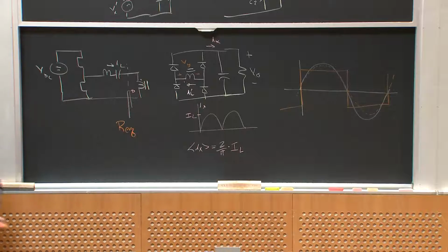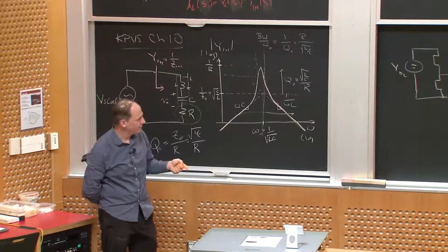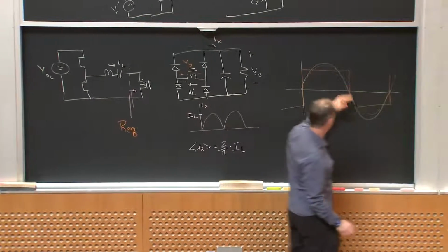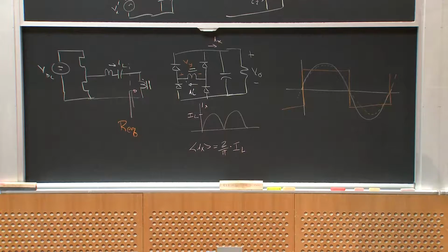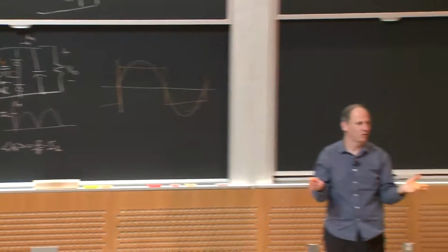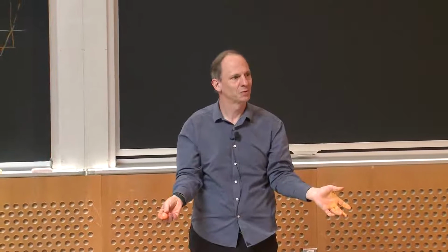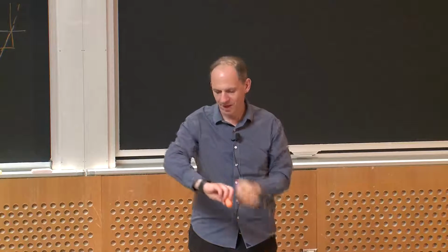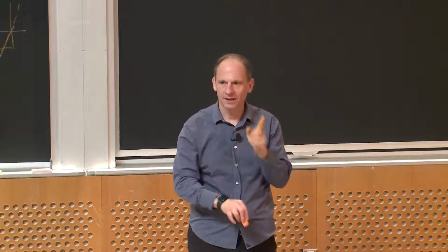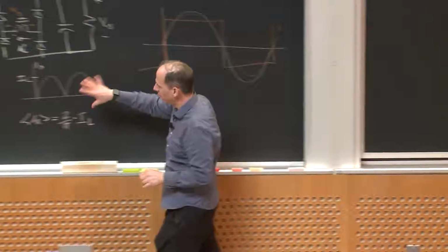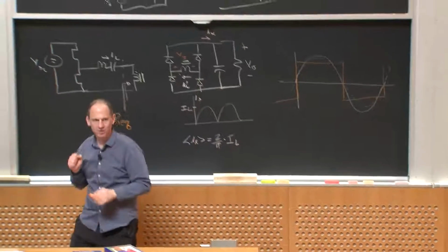And I'm back exactly to this original model I had. And the only thing I've done there is I've said, I don't care about the harmonics of this because as long as the current's close to sinusoidal, almost all the power is in the fundamental. Okay? So I've kind of run out of time there, but I'll come back next class and we can talk a little bit more about how we might model DC to DC converters in this way.